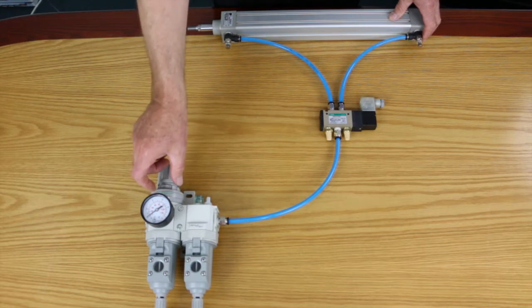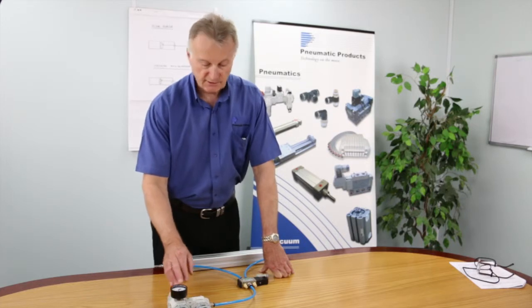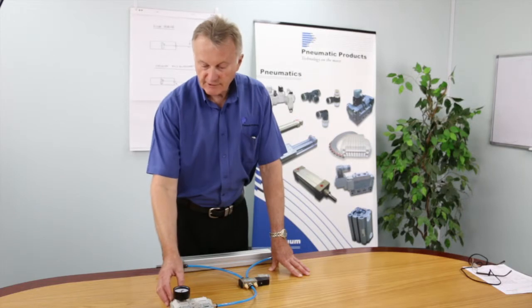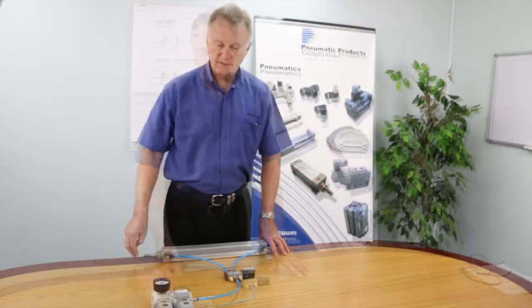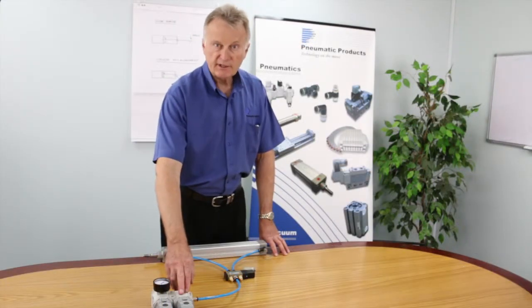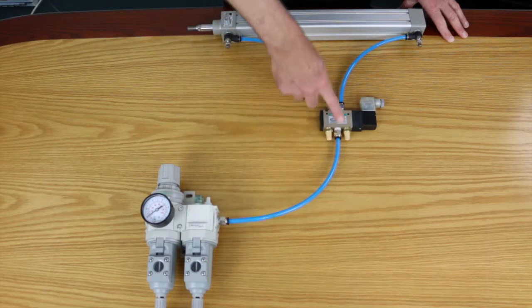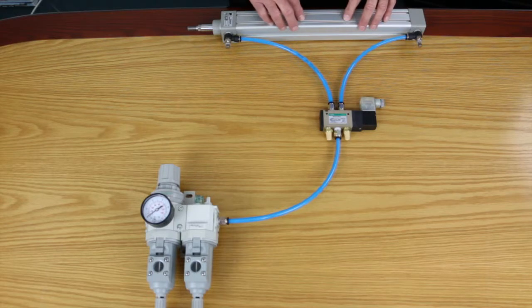If you're still having a problem with wild fluctuation of pressure, then it's likely to be something else. The other thing to consider would be that the piston in the regulator is not moving freely due to contaminants, so that would be something to consider as well. Another is that the lubricator may have run out of oil, and therefore we're not getting lubrication through to the air cylinder. The piston seals have more friction, and therefore the cylinder has slowed down.